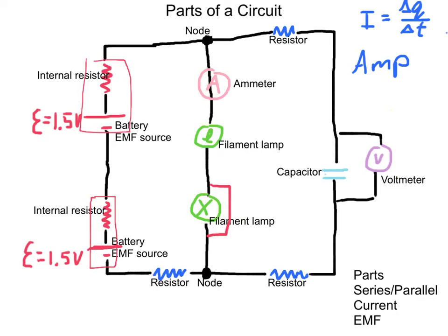Now, this isn't that big of a deal here, except your lamp wouldn't turn on because you have other resistors. On the other hand, a much bigger deal comes if you have a connection, let's say a wire that runs here. If you have a connection with just wires, this sort of situation could be a problem because the current would come out of the battery and then take the path of least resistance. It technically would divide, but this path has a straight wire in it, next to no resistance. So it's going to, for the most part, skip this lane, come over here, skip going that way, and just come down the wire, very low resistance, and then check it out, it only has one resistor to go through for a circuit that was probably designed to have many, many things that resist electricity on that.